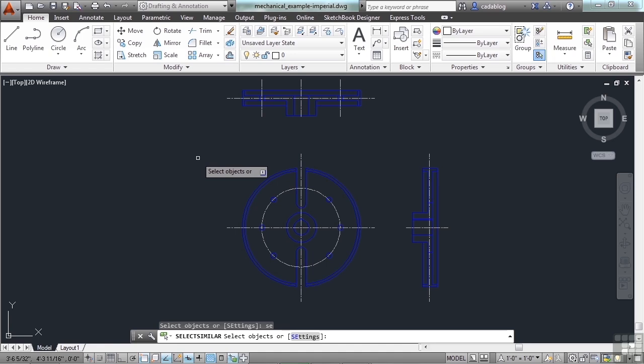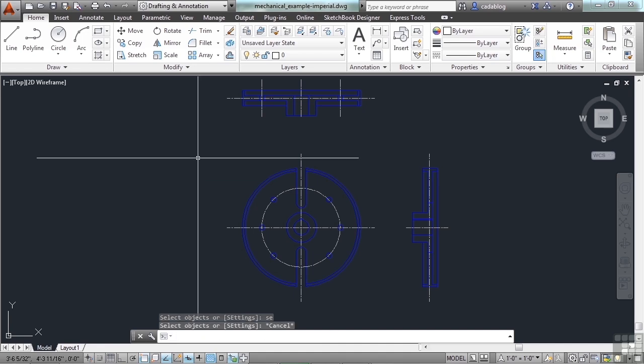And there you go. AutoCAD gives you several different ways to select objects. Remember some of those whenever you go to Start. You have your crossing window and your selection window. You'll use those most often. Plus, you can pick an object one at a time. You have the fence command, you have the Select Similar, you also have your window polygon, the WP, or the crossing window polygon, which is CP, and you have your Shift key, which you can use to unselect things. This will save you a lot of time and effort through your drawing process.